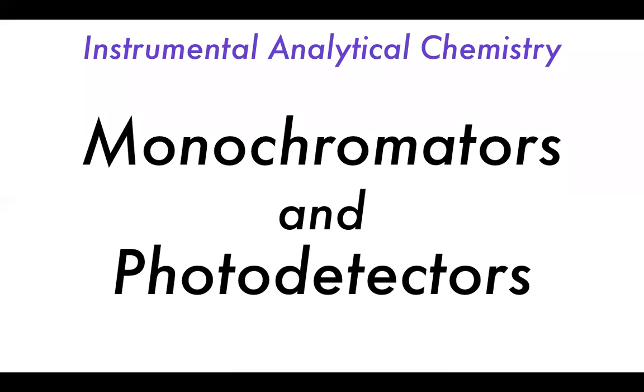As well as that, we'll be looking at photodetectors, which are transducers in our optical measurements. These are the things which are going to take the light which we have produced in our processes so far and translate those into electrical signals for our computerized detection systems, or even just in our analog detection and readout dials. So again, monochromators have 5 major parts.